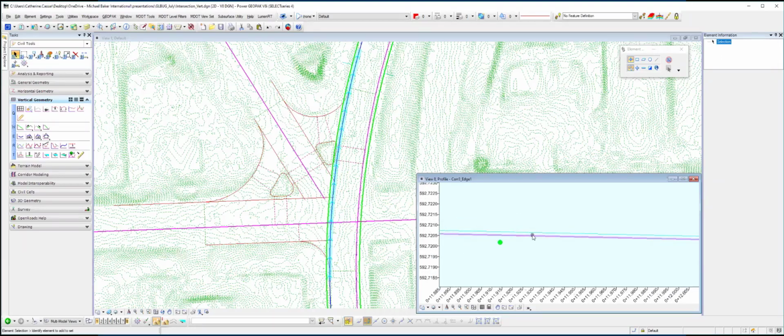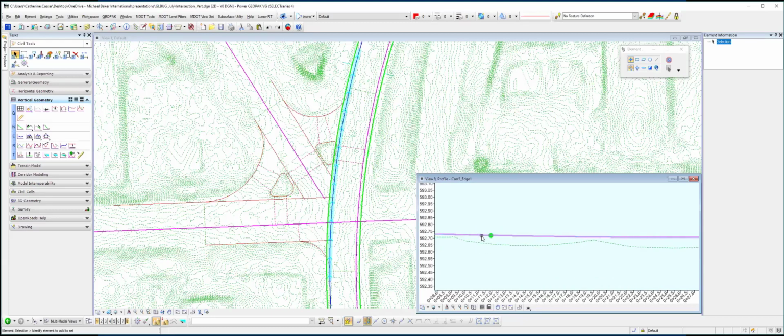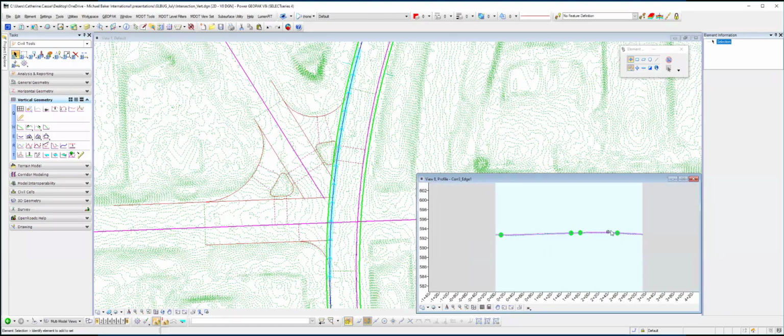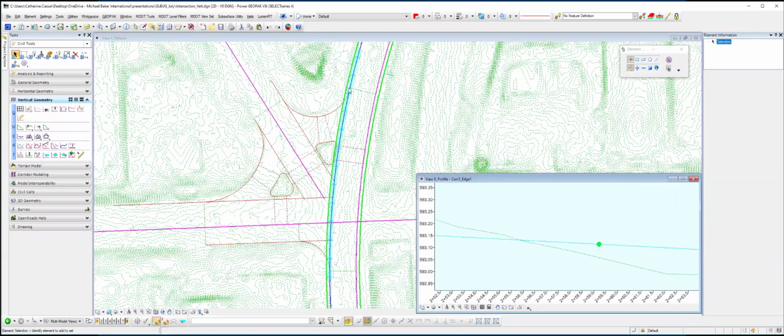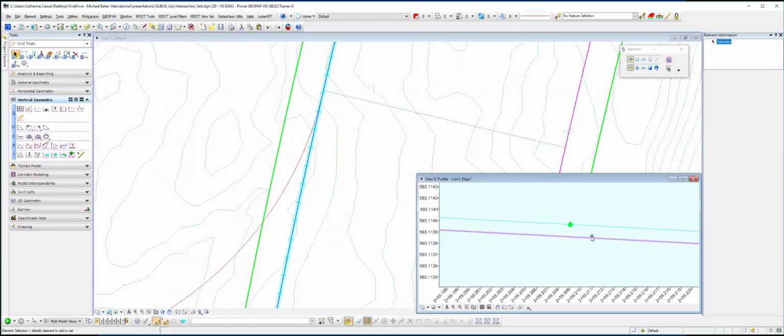Just because, especially when you're dealing with vertical curves. If you just have a tangent, you probably won't see much of a problem. And we have that here on the northern edge, this limit line up here. Here, I only have two solutions essentially. Here's the modeled edge and where it comes in. This is the main line at a set 2%, and this is the point that is at 2%.